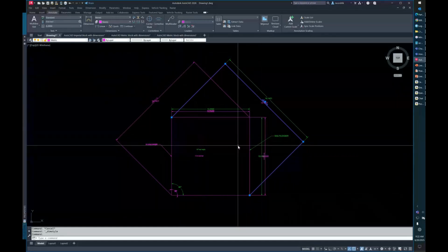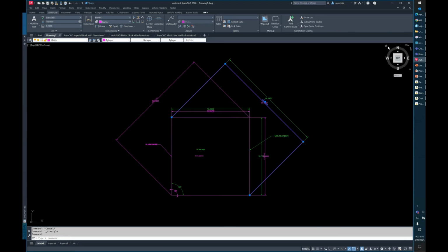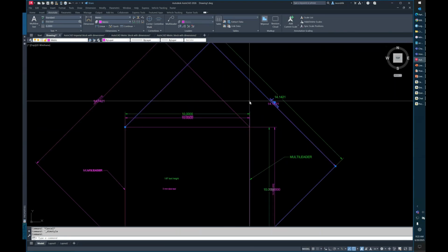I kind of showed you the pitfalls. Those are the big ones. Those are how we get things to come in a lot easier: either making sure my styles are all the same name, making sure that the drawings are all set to the correct unit so it automatically scales on insert. And if I can't get there from here, or I can't change enough styles to match what I have, I use the minus DWG units to convert the whole thing. And then I will come back in and make those couple of quick modifications. Easy peasy, I'm done. Ask your questions, but any questions regarding imperial to metric, metric to imperial?